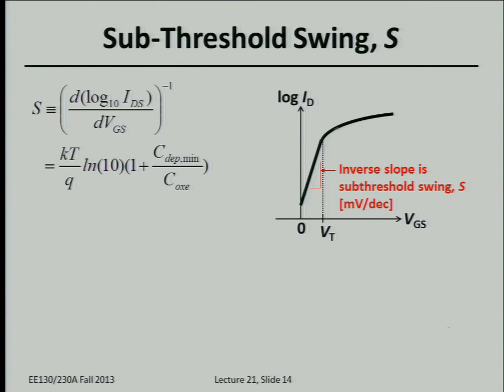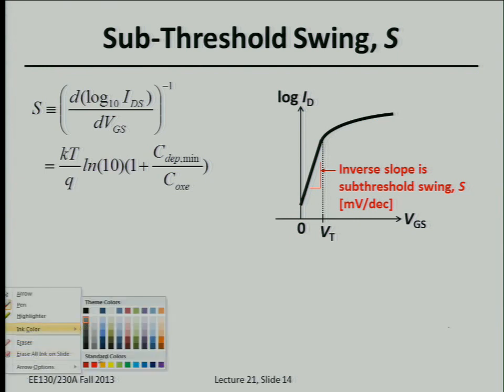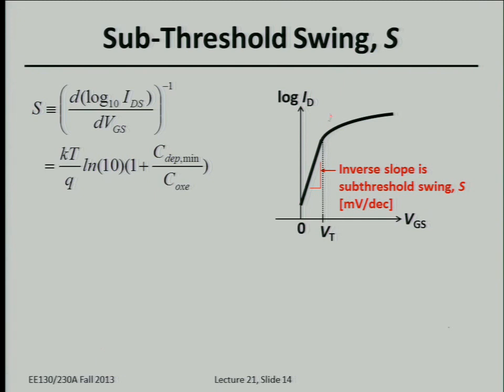And above the threshold voltage, where the current becomes limited by the rate at which carriers can drift, it becomes more linear like before. Okay, so above threshold, it's more linear, right? And then below threshold, you sort of have a log dependence of current on the gate voltage. Okay, so a parameter that people like to report when they talk about advanced transistor technologies is the subthreshold swing. Okay, so that's S, and that's defined to be the amount of gate voltage change needed to cause the transistor current to change by 1 decade. In other words, by 10x.